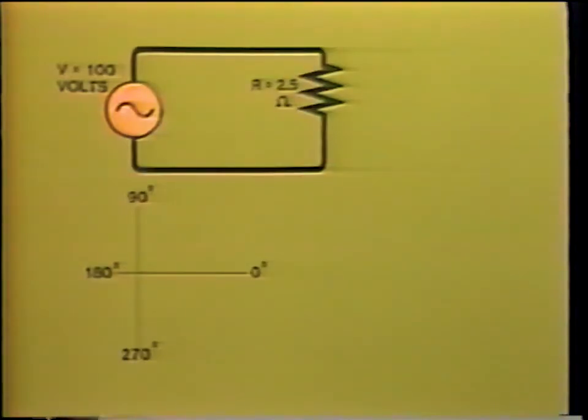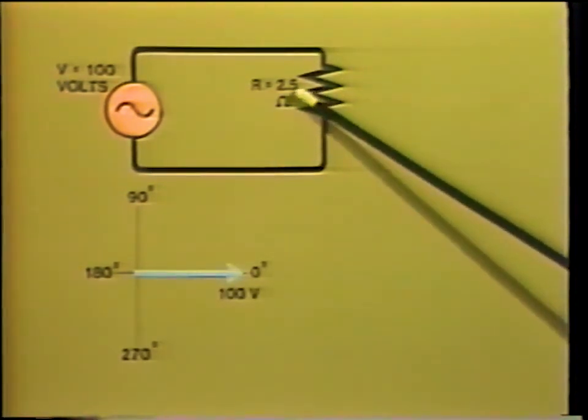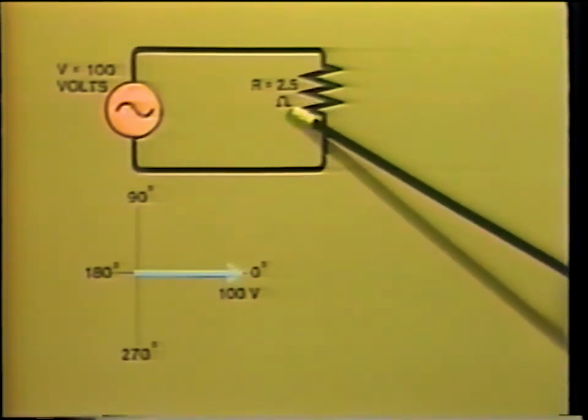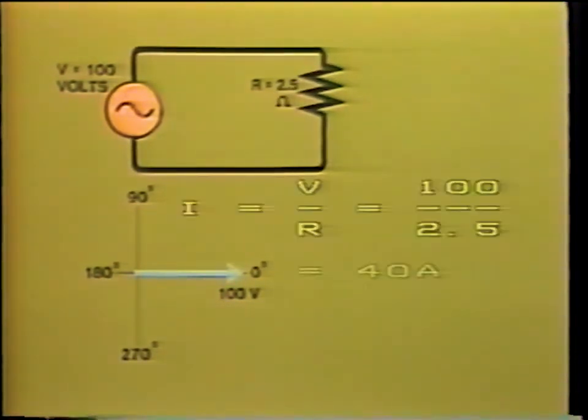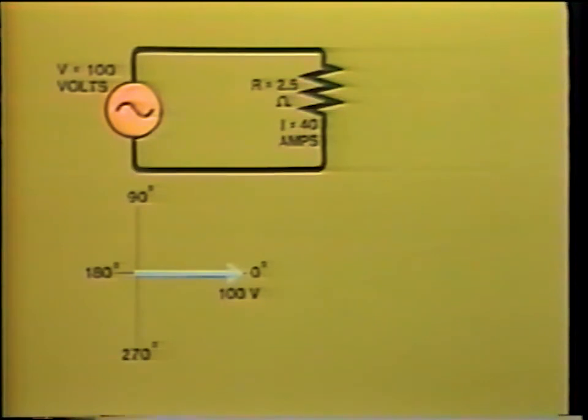So, now we know the effects of pure resistance, inductance, and capacitance. So, let's now look at an example where we have a circuit containing all three quantities. We will start with resistance and then add the other circuit components in parallel as we proceed. We have a voltage of 100 volts. The resistance is 2.5 ohms, and ohms are usually represented by the Greek letter omega. So that will give us a value of current through the resistance of 40 amperes.